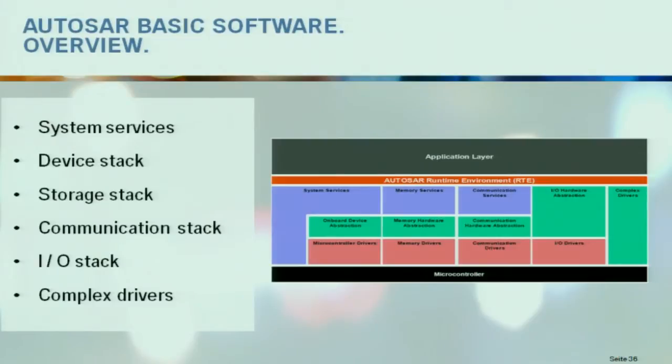Then the communication stack handles all the bus systems, even the local SPI, for example, and also the CAN bus, FlexRay bus, and so on. And the I/O stack, meaning if you have some AD converter or digital I/O, this is handled via this stack. And the last thing is the so-called complex device drivers or complex drivers, which are used to bypass all the other operating system services.